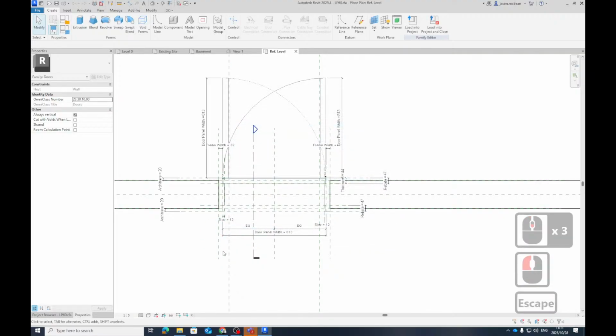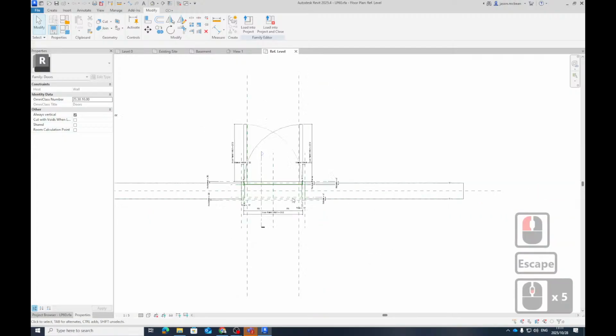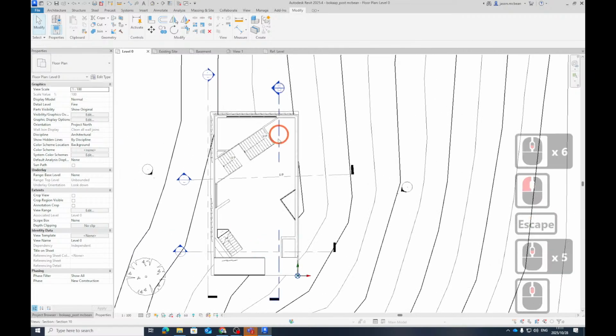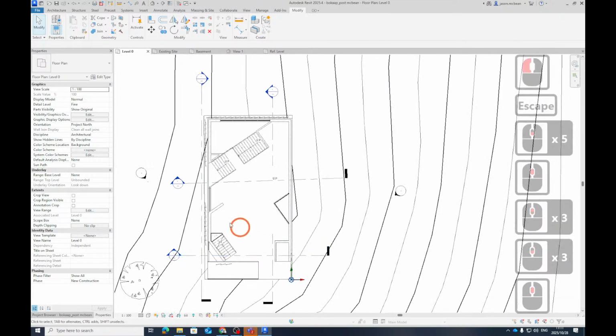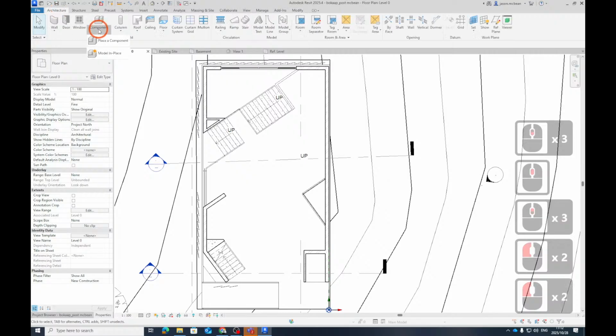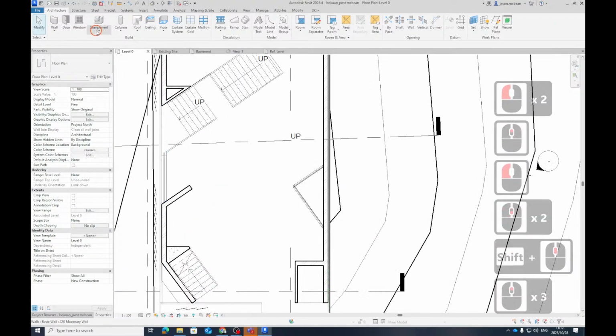Everything is driven by these little, so that's why. So if I want to add a window into the door, it's going to be so difficult, but anything in Revit you can model in place. You've got this function to model in place, by which I mean you can model an in-place door